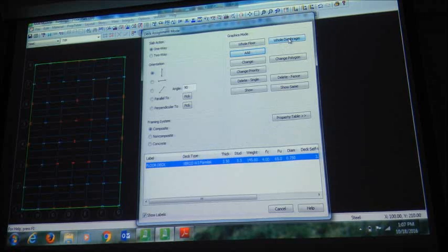Okay? And I'm going to use a membrane or shell diaphragm. Again, membrane means when it's used for gravity load, and diaphragm is when it is used for gravity plus lateral. So I'm using it as a membrane. Okay, and if you see, the deck penetration or deck opening is still there. Are you with me so far?